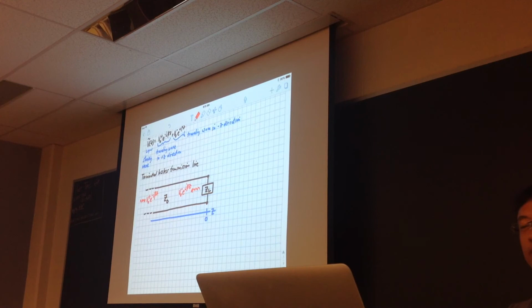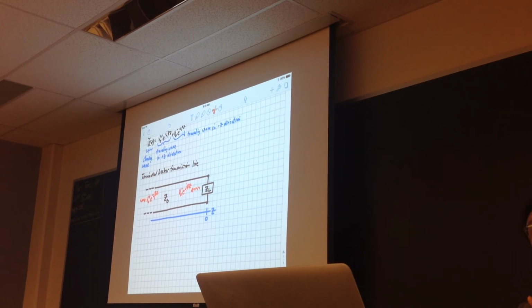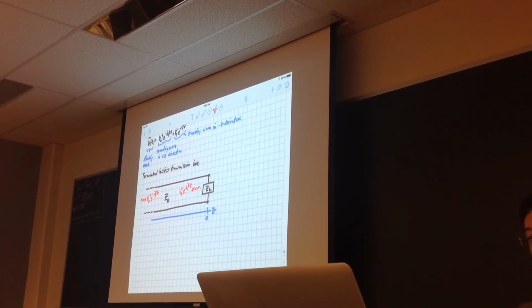Physically, that's how you can think about it. You have some input wave on the left, and depending on the value of ZL relative to Z naught, you're going to get some kind of reflection. It's a wave, right? If it sees an impedance mismatch, or what we would call an obstacle, then waves tend to bounce back and produce a reflection. The amount of reflection is going to depend on the value of ZL relative to Z naught.